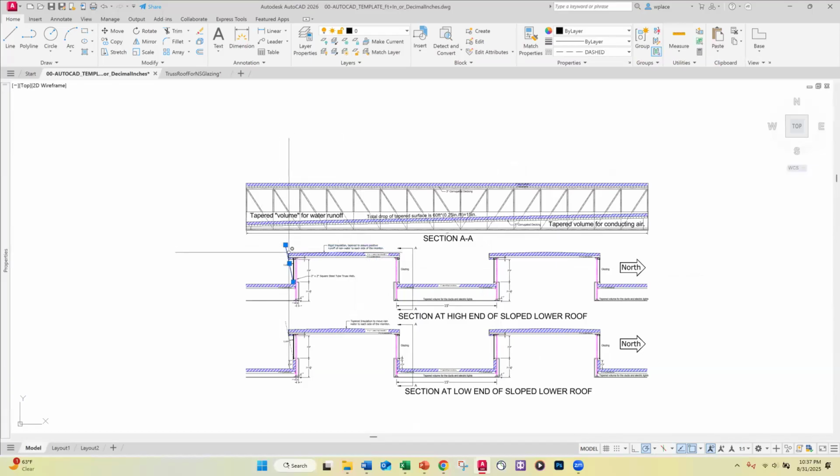And if it's just for view glass and you're trying to stop glare, that profile angle might go all the way out to 30 or 40 degrees, depending upon how urgently important it is to you to protect the space inside from glare.